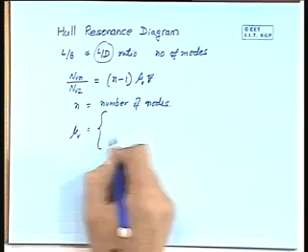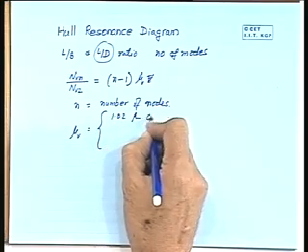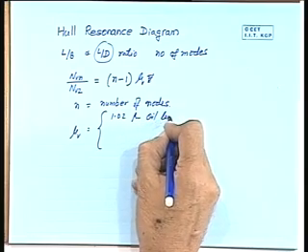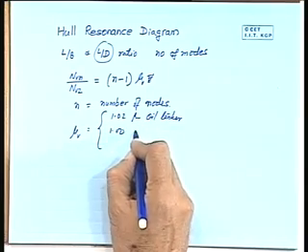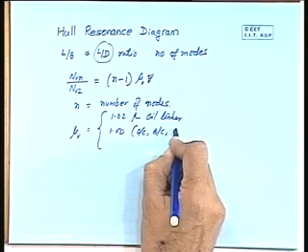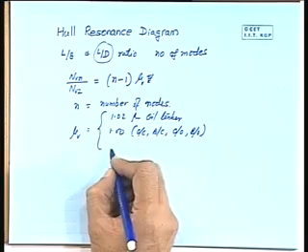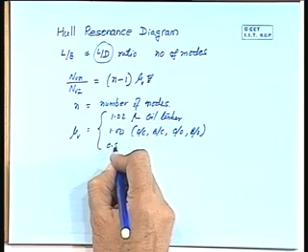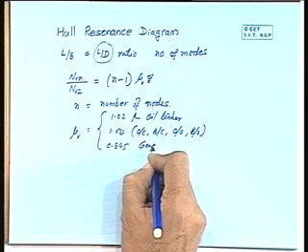Mu v is a coefficient which is 1.02 for oil tanker, one for oil carrier, bulk carrier, oil and ore carrier, bulk and oil carrier, and 0.845 for general cargo.